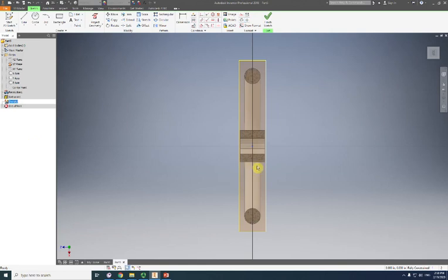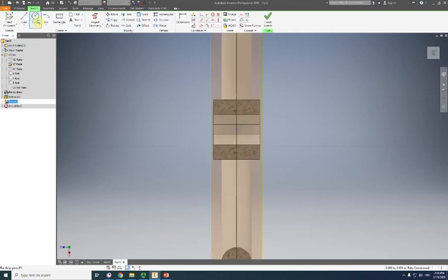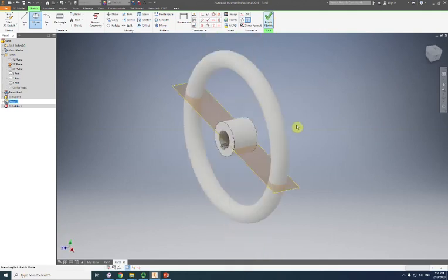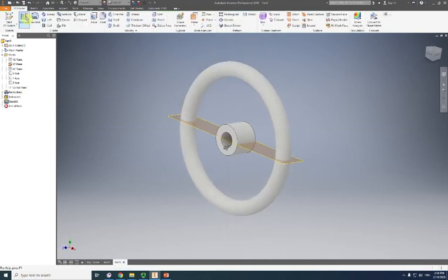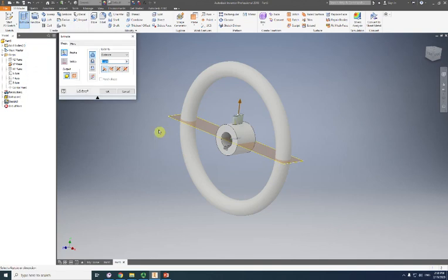Okay, now we want to draw an ellipse here. Let me go to ellipse, center of the ellipse, say here, major axis, minor axis. Just an example. I will come back and do it correctly. Okay, just finish. Now we agreed that we'll make what? Extrude. We want extrude down. How much the height? No need to know how much the height. It should connect between the spoke and between the hub and the rim. So say 5. Good in this case.